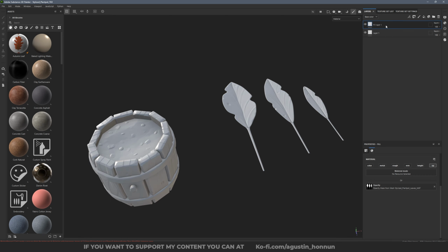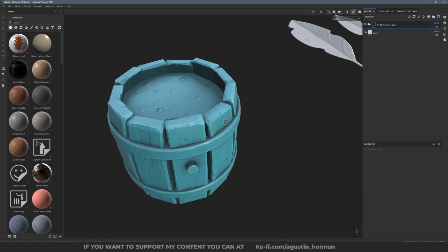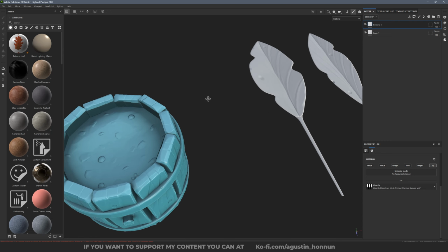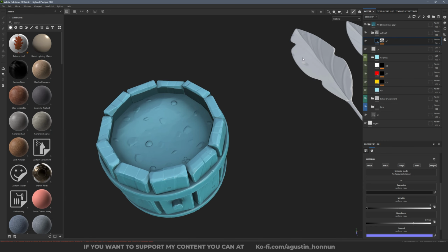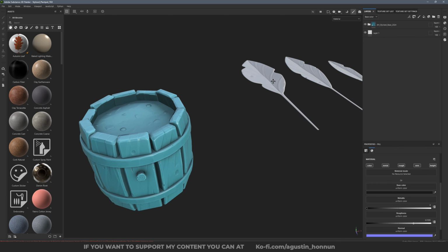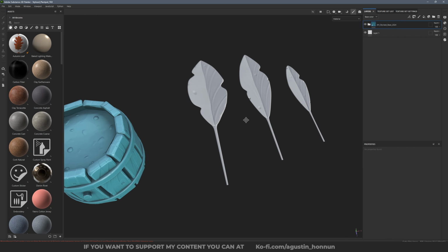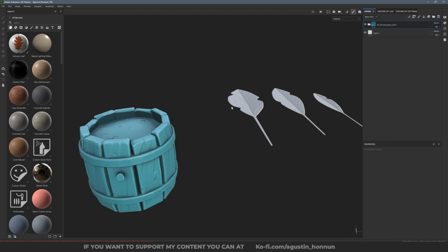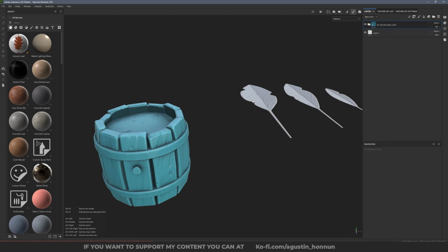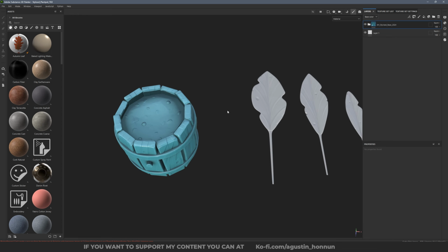I'm going to add this material on the barrel. So if you want to avoid going to the lips and back to the barrel, this will take you some time to load. So as we are going to be using Vertex paint or color selection, because we bake the ID map, I'm going to show you a very interesting way to texturize without moving from materials to other.